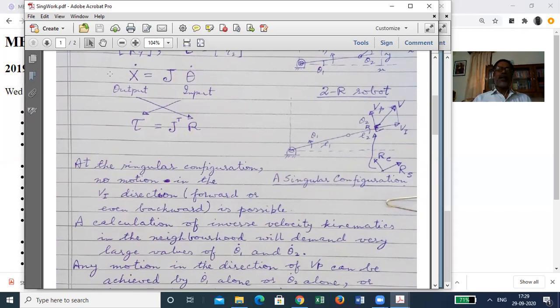The reason is that when you try to put that velocity here and you try to solve this system of equations, this Jacobian transformation turns out to be singular, and Vp falls in the range of J, and that is why a singular configuration, singular matrix, and the known vector on the other side of the equations is in the range of it.